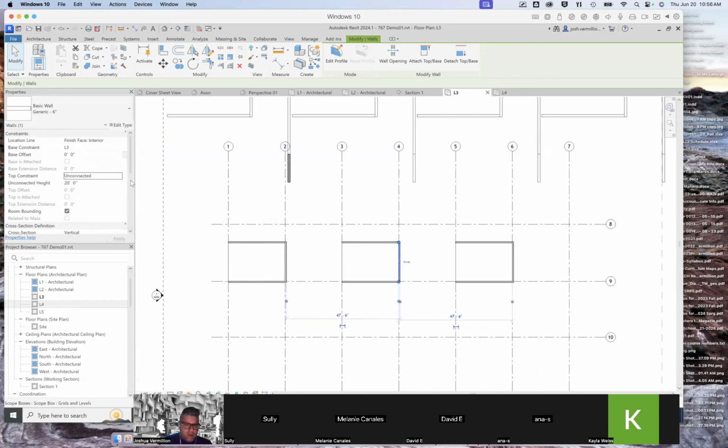Compared to, let's say, Rhino, where you just down and dirty start modeling things and model geometry, Revit becomes a little more of a going back and forth, the intellectual exercise of looking at the big overall ordering system, grids, and then putting things in, the big things and then the detailed things. But always trying to make sure that you build the big things off of the grids that you align with, and then you build the small things off the big things that you already modeled, right? So that everything's interconnected. And as you make changes to one thing, all the changes propagate throughout, without having to remodel or fix a bunch of things.